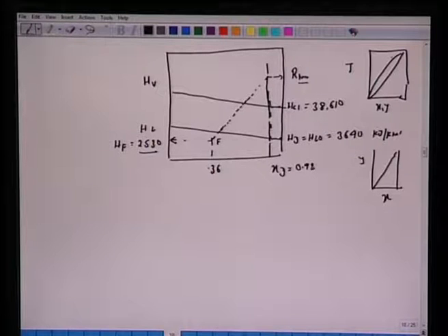So we have this XY diagram, or we have this TXY diagram, which is like this here. Given X, we can calculate Y right here. So we have to find that combination of Y and X which passes through this F. From here we get this R min.